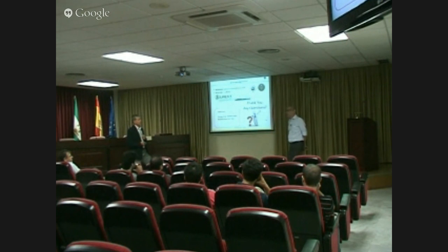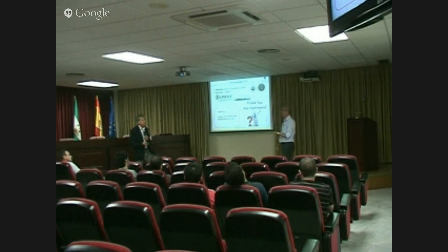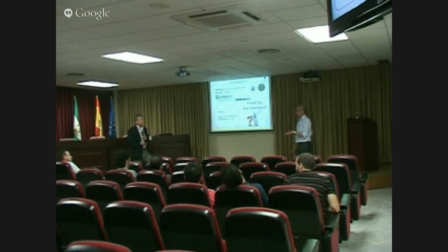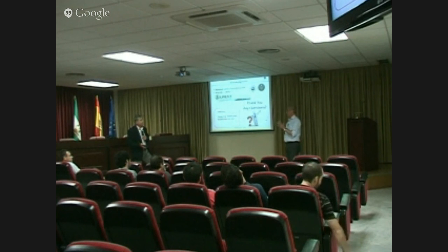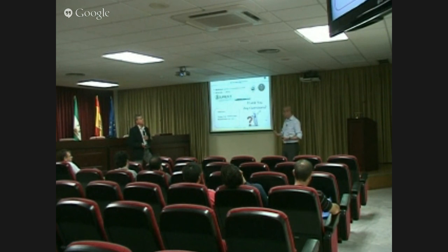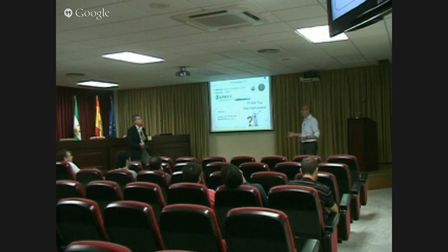On the other hand, at least for the time being, the infrastructure supporting SCADA, I don't know about relaying, versus the infrastructure supporting the phasor measurements, they are not the same. So in other words, there may be situations where a storm comes through and you lose SCADA, but you may not lose PMU connectivity. So in that case, this may be just a complementary solution. If they're using a different channel, yeah.